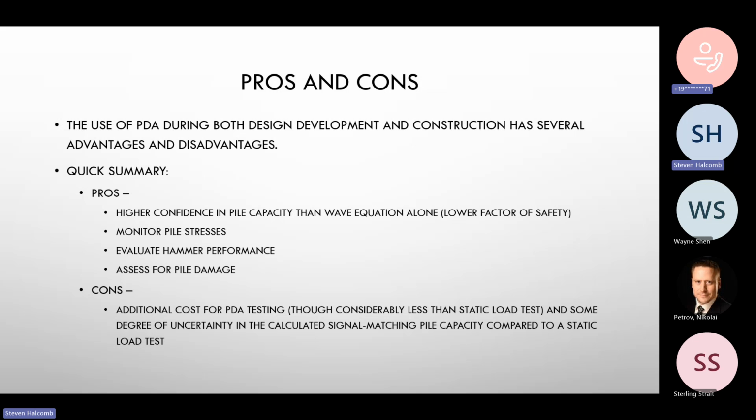I've seen projects where it's like a pedestrian bridge, a two pile abutment, big H piles down to really dense material, only being loaded to very small loads. And so to mobilize a contractor out to do the PDA might be overkill, because the piles can handle lots of stress. You're not going to hit them that hard. You've got good bearing, so you don't really need to worry about capacity. But it's useful. It's in our standard spec. It's what we presume is going to happen on every project. But there are certain times when it's not really needed.